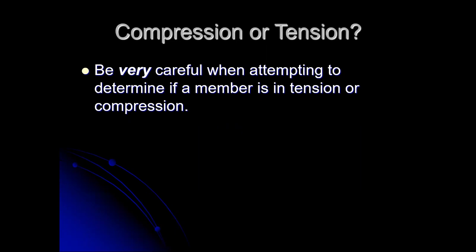Flip that around and think about a spring. If I take a spring and compress it and hand it to you, the first thing you're going to feel when you hold on to that spring is that it's pushing your hands out, and you're going to have to push harder in to hold on to it. A member in compression tries to expand back out, so it tends to push its supports out.